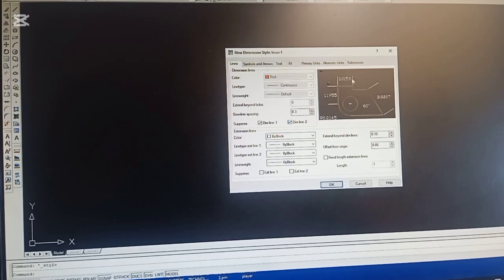Now when you suppress both sides, you will not see any arrow showing, so you don't leave the suppressing the way it is, so that after your dimension you still see a small space outside. You understand? So that's it. So you now go to your extension line. Extension line is, after doing your dimension, the one that comes outside. What does it look like?